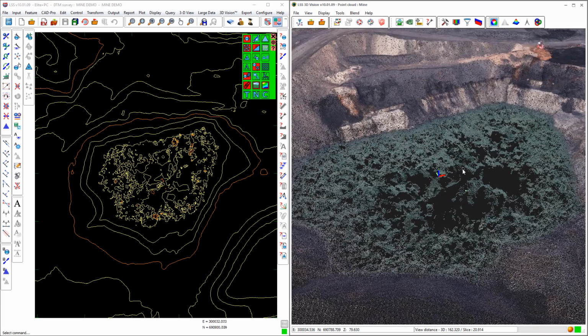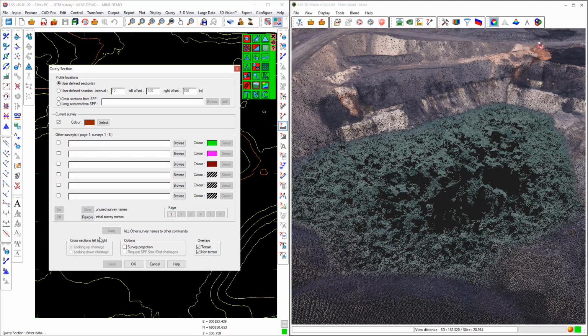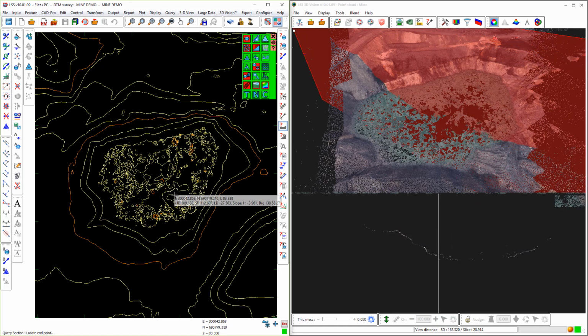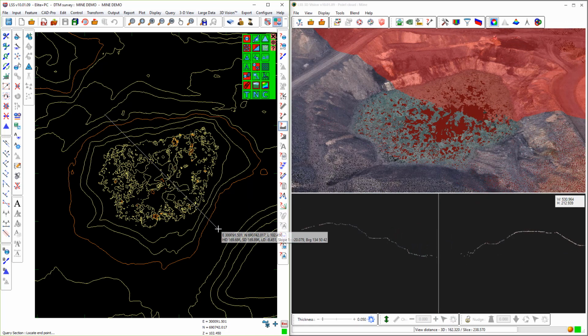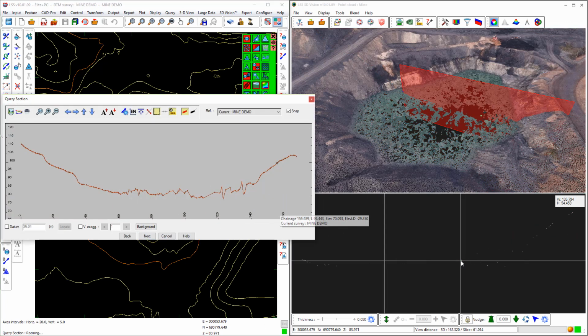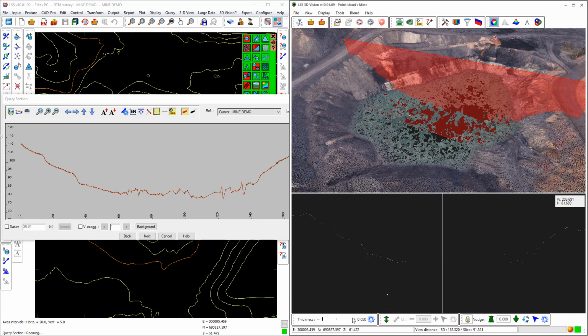And because this is photogrammetrically defined data or derived data, it doesn't like moving water, and it will confuse the model that comes out of the photogrammetric software. So what we need to do here, because you can see this should be flat, and it isn't, quite clearly in the bottom right hand corner there in the slice view in 3D Vision. So the best way of sorting this out is to use the LSS tools to remove those points.